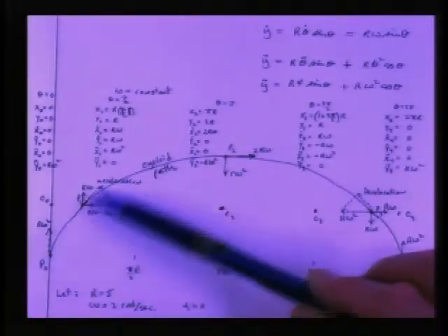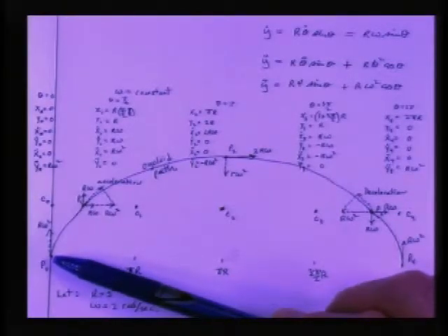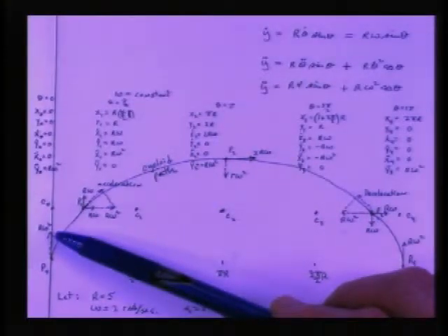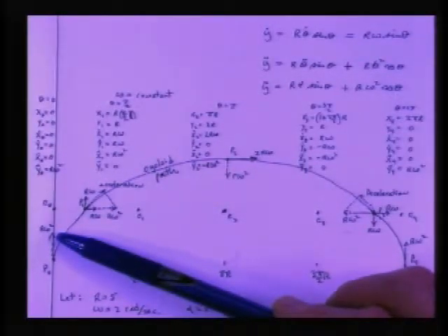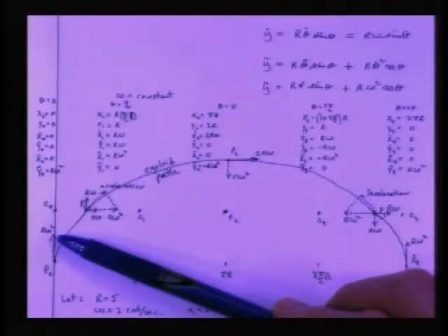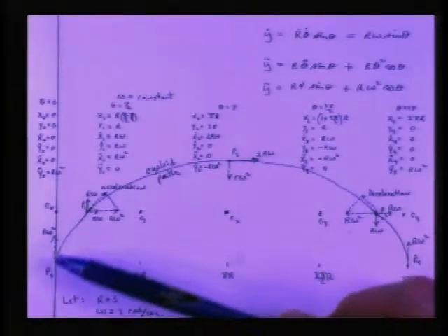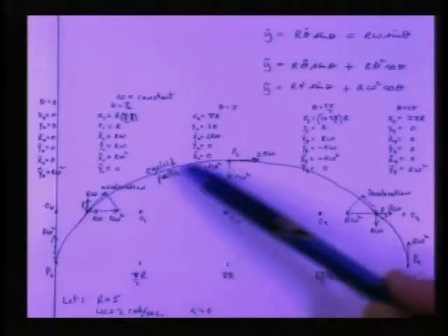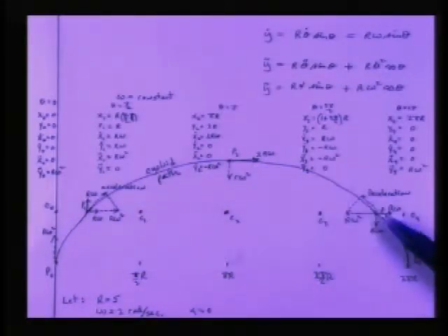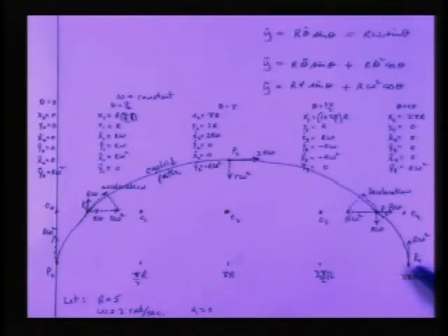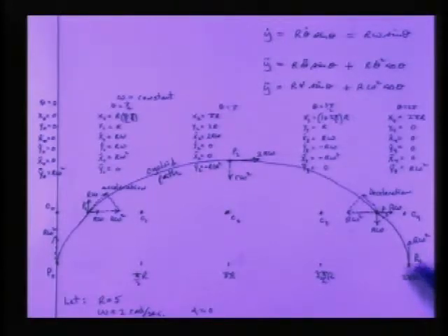You can look right here when the bottom of the wheel is just touching the ground. The only acceleration it's carrying is r omega squared, straight upward. When the wheel finishes its complete rotation, that point has come back down to the ground, and it comes in vertical, and its acceleration right there is upward again.